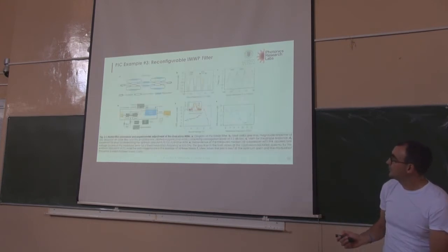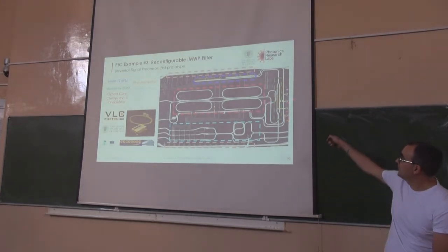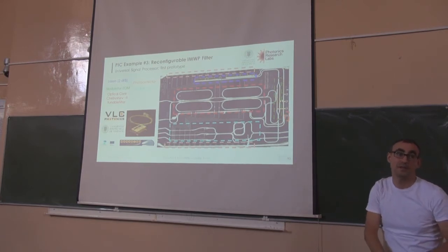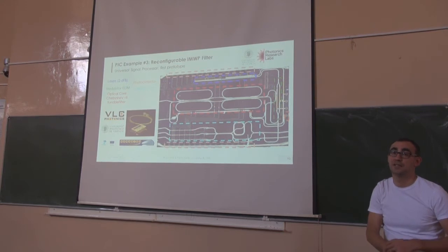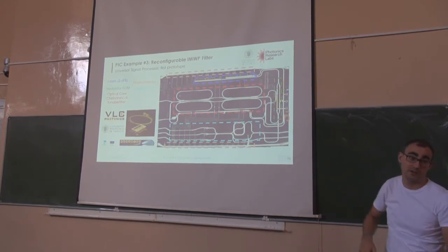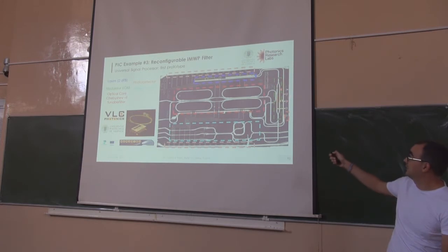Another important issue is RF. We have here the modulator patch, and here the detector patch. We found that we had a lot of RF crosstalk. We still have not determined whether it is on the photonic chip or on the RF subcarrier. But we did this adhering to a packaging template, and the packaging template states here RF and here DC.